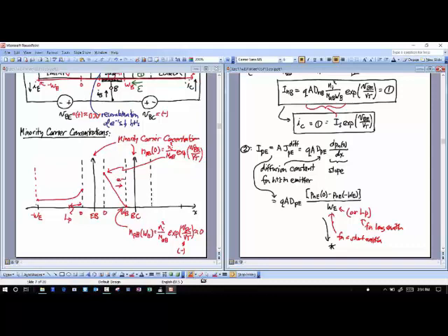It is kind of confusing here because, right, this WE would be, actually I could do this, it's color-coded, right? So WE would be if I assumed this variation of minority carriers, holes in the emitter. Whereas LP would be if I assumed this variation, which is what it would take if the emitter were long, if the emitter width were large.